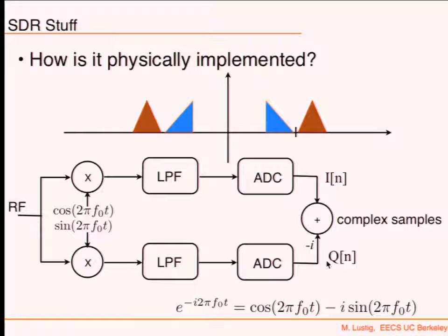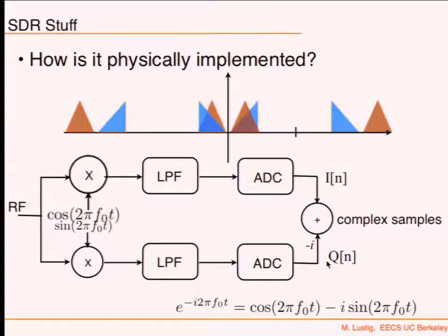So let's look at the top part and see what happens when you do this. When you demodulate, the spectrum is shifted in one way and the other part is shifted the other way, right? Because you have two delta functions. And now they overlap. And really what you get is the symmetric spectrum. You can decompose your spectrum into the even part and odd part. And so this is really what it's doing. Now your spectrum is the even part. And yes, it's real. Now you've got real samples coming out, and those represent the real part, the symmetric part.